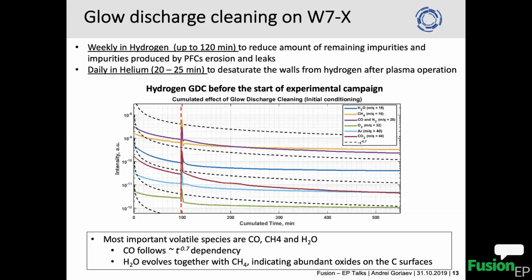Also the intensity of the current that you put on the RGA filament will change the average ionization states of different species in different ways. And yeah, you got to be very careful.